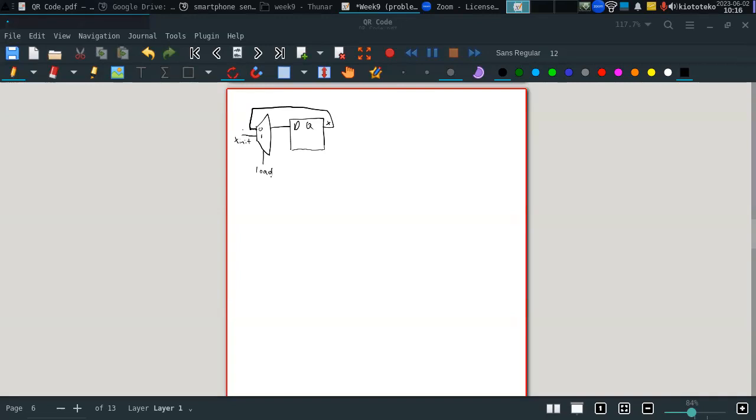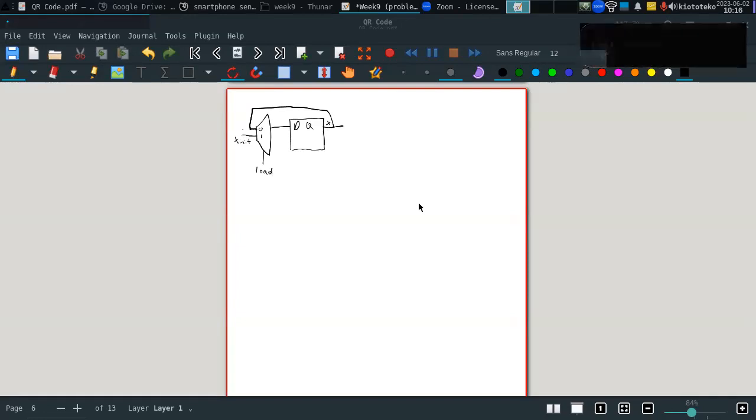We'll have one of the things they require, to maintain X in a register. We're doing that right now. And obviously we can either load a new value or just maintain the state of X there. Then we also have Y and I, which are our two variables. And I'm just going to put two flip-flops here.